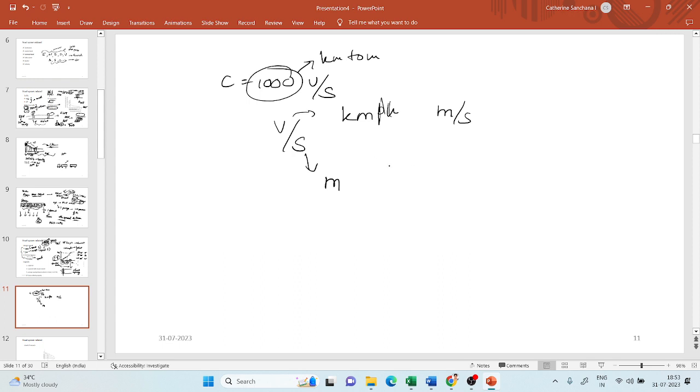Okay. Now, if you see the units of this, it will be per second, right? So capacity will be in number of vehicles. Number does not have any unit, right? So vehicles per second, or mostly it is not given in seconds because it is vehicular count. You cannot give in seconds. You will give it in hours. So you will convert it to hours and you will say vehicles per hour. Okay, so that is capacity.